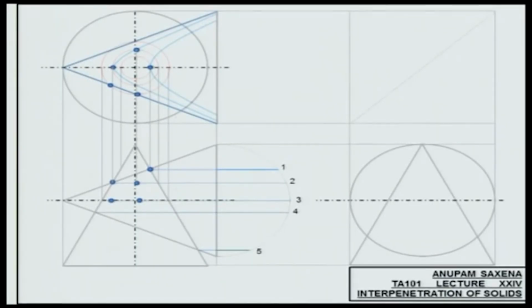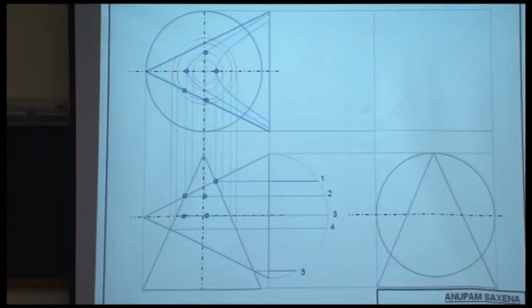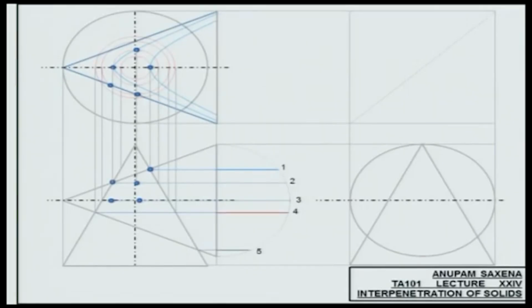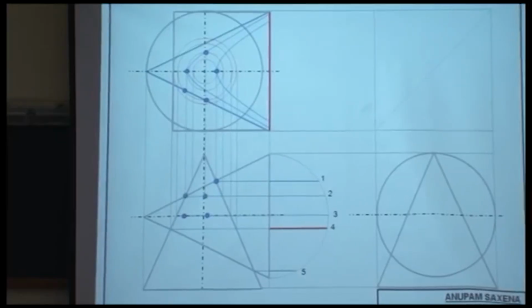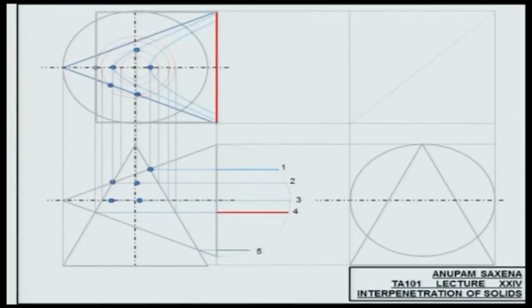Plane number 4, again, the vertical cone is going to be giving me a circle. The horizontal cone is going to be giving me a hyperbola. So you need to draw that hyperbola. I'll quickly go through that. So measure this distance, make that distance over there and over there. Draw this box, the same construction procedure.